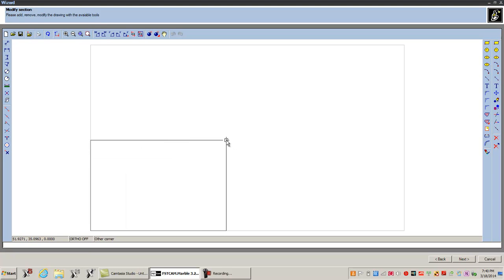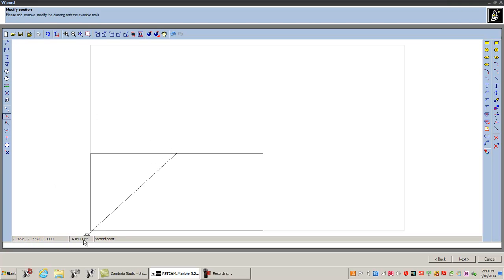All right, and it's 66 by 30, okay? I want to make a radius. Many ways to do it. I'm going to make a line from, I'm going to turn on the snap middle tool, the middle, and now I'm going to turn ortho on. I'm just going to move up and I'm going to go 6 inches.